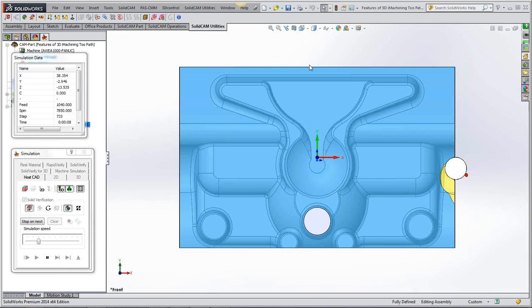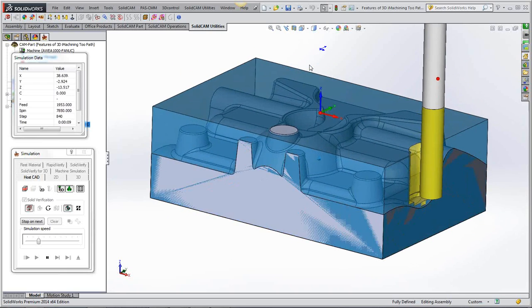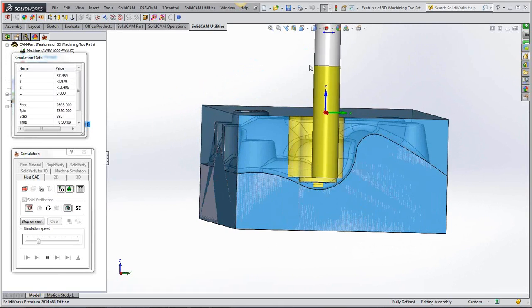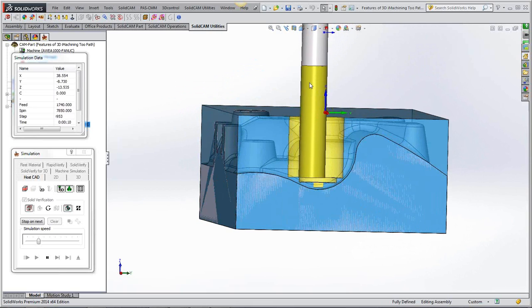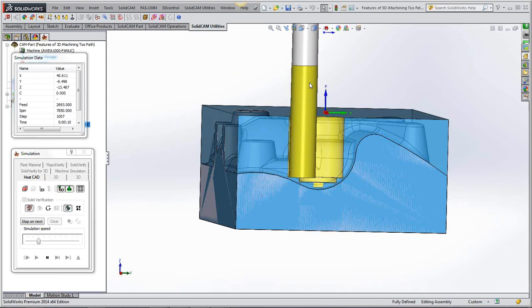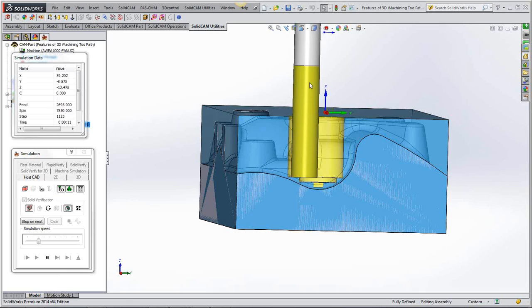And now you can see it's changing the shape now to suit the shape of the model. It's stepping itself up slightly now. It started down at the bottom, but because of the proximity of the shape of the mold there, it's had to step up. This is what I mean by step ups. They are normally step downs, but SolidCAM, I mean iMachining, does a step up.